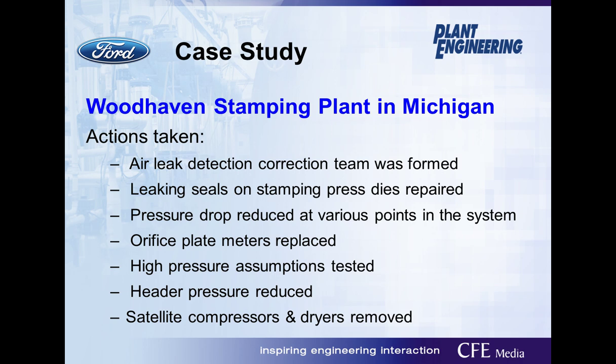A case study that I had was the Woodhaven stamping plant that we worked with. Again, they did leak detection. They repaired seals in the presses. They looked at the pressure drops and reduced them at various points. They removed orifice plates and put in insertion meters. They also worked on high pressure assumptions.